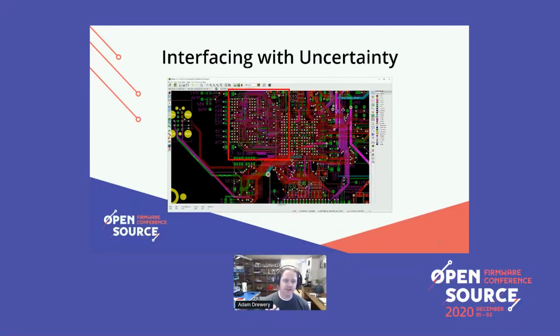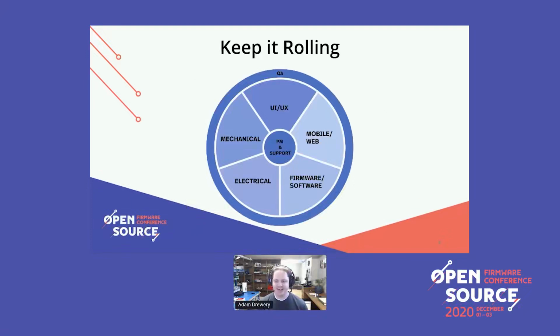And then because they're such high frequency, they're really sensitive, and so you have to have much more expensive and advanced equipment to actually debug them if you're in that kind of situation. Suddenly getting that wrong costs you another week or more, and at least $5,000 for a new round of circuit boards. That's really hard to deal with.